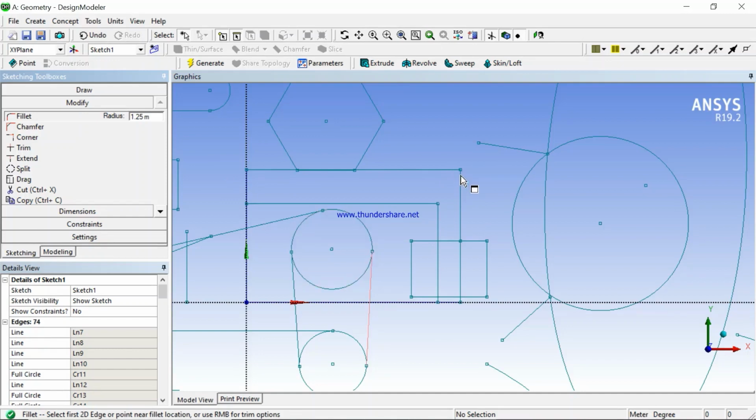At this corner, if you don't want something sharp, you click on the fillet. You will select the first line and the second line for the corner. So you can see the curve is formed. This is what we call a fillet. It is to smoothen that curve. Maybe you're doing finishing on a weld, a window, you want to smoothen it so that it is not sharp. Most of the time for beautifying and safety purposes, that's how we add a fillet.